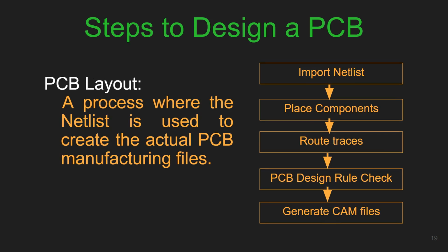The next step in this process is the PCB layout process, which requires import of the netlist, then the actual placing of the components, then routing traces, PCB design rule check, and generating the CAM files.